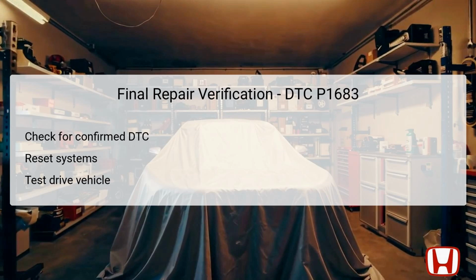Begin by checking for any confirmed or pending DTCs using the HDS. This process will show if the systems are functioning properly post-repair. After verifying the DTC status, reset the systems and clear any recorded codes to ensure no residual effects from previous faults. Upon completion of these steps, proceed to test drive the vehicle under typical conditions.